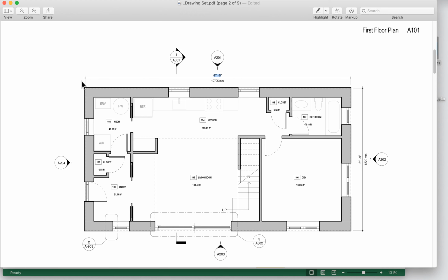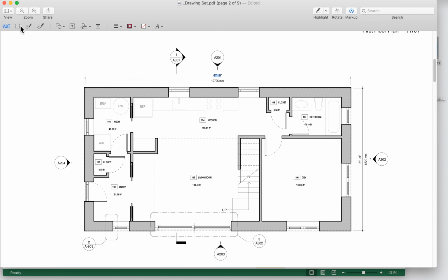Well, what it's saying is, PHPP, I only want you to input an edge if it is exposed to the outdoor air. So what it's telling us to input are exposed edges only. What would be a case where we would have an edge that's not exposed? Well, consider a row house.